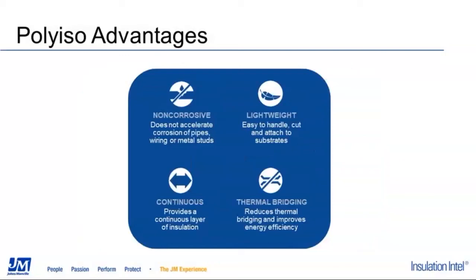We have a previously done webinar on continuous insulation that discusses the purpose of that and how it combats thermal bridging. Just put very briefly here, thermal bridging is when heat or cool transfers through the stud medium, so wood or steel stud. If you envision a standard wall construction, a lot of that wall is going to be made up of stud material.